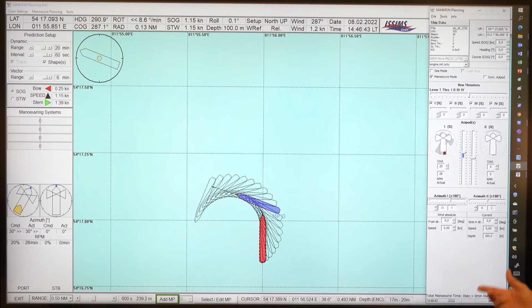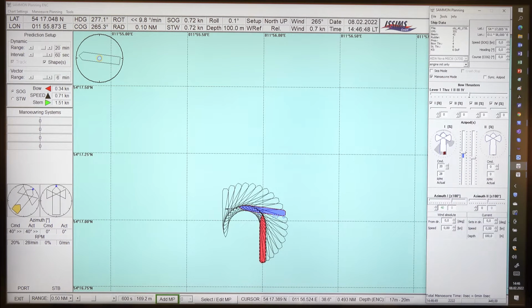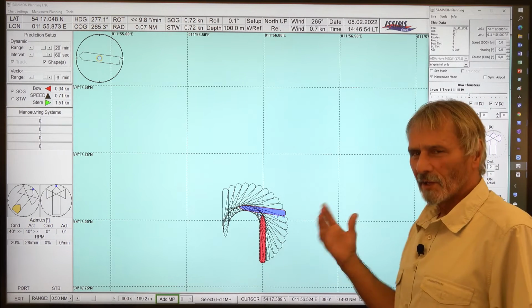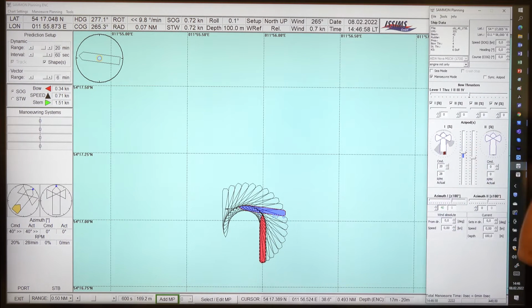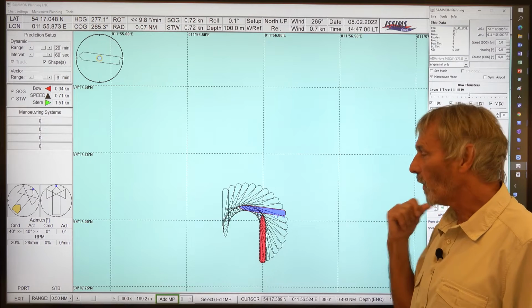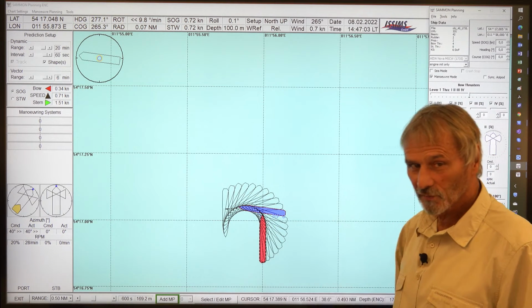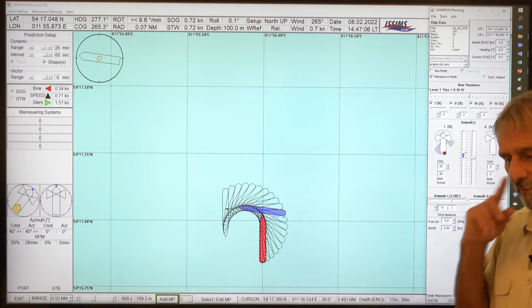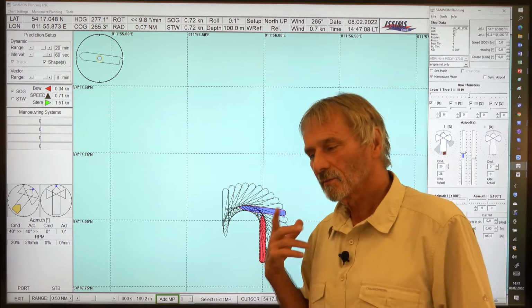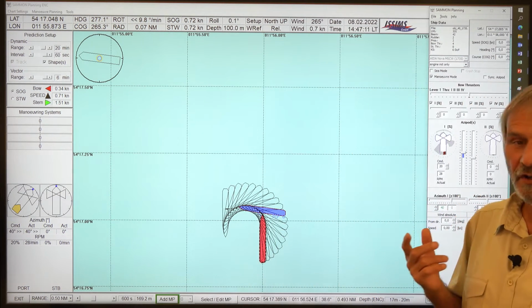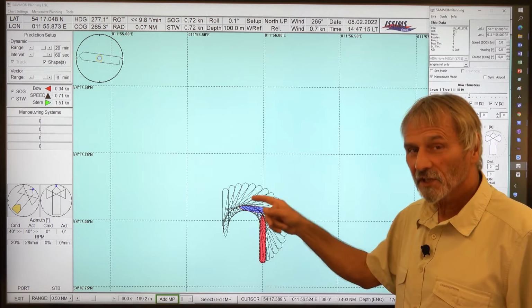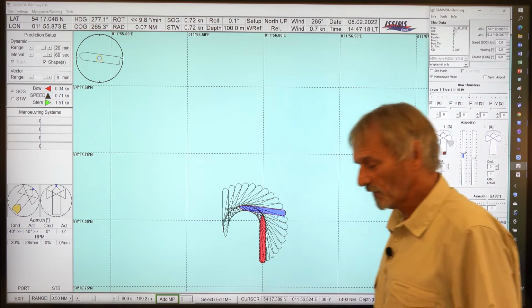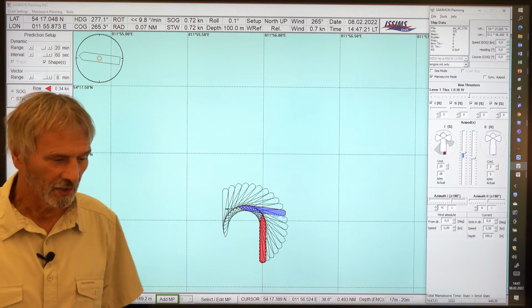Okay, if we go further, then maybe to 40 degree, and what you see is, and you might wonder, the pod clearly is creating a force to this side, to the outside. So why the ship is turning then to the port side, to the counter side? You might remember my movie about the turning circle dynamics, where I explained the ship is turning to this side because of the lift forces due to the drift angle.